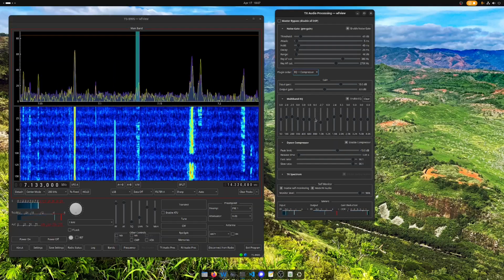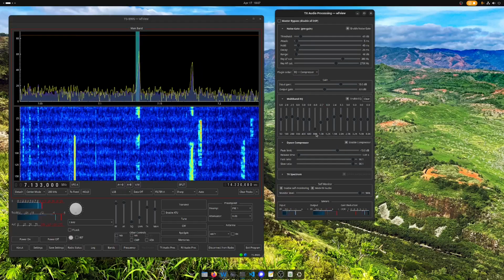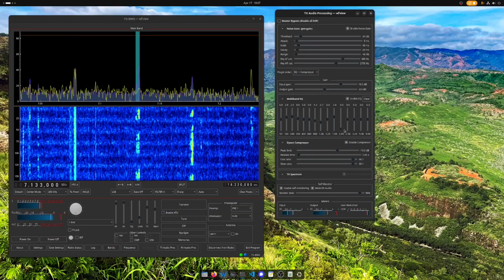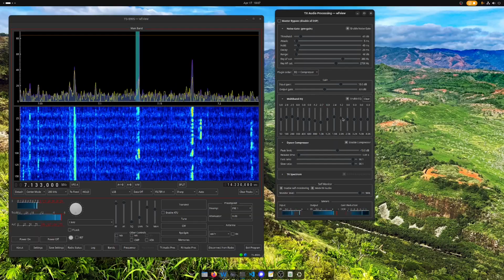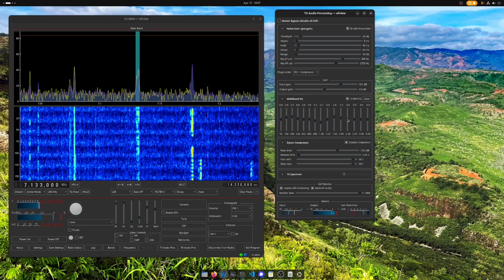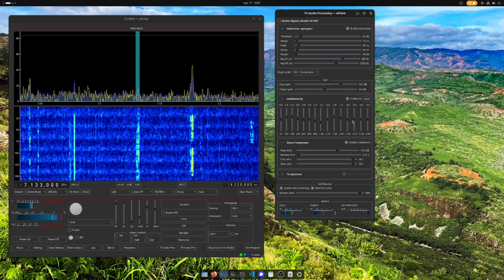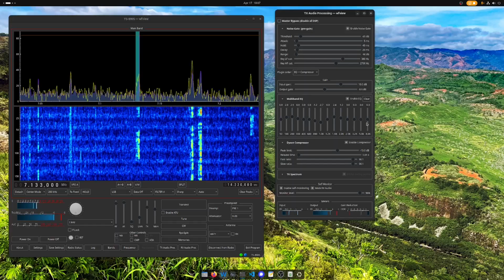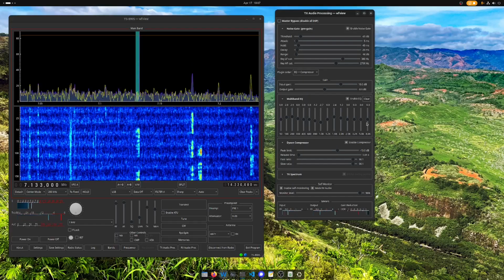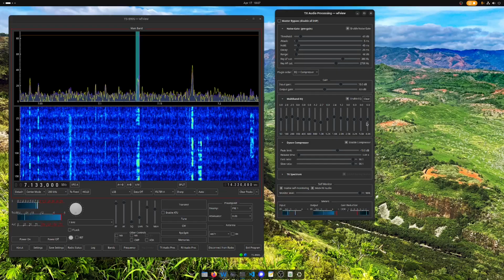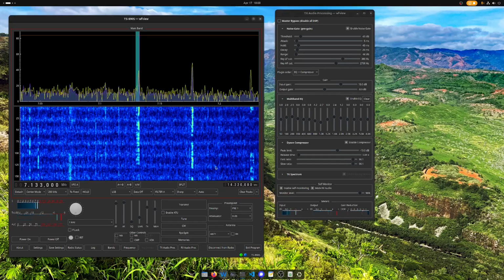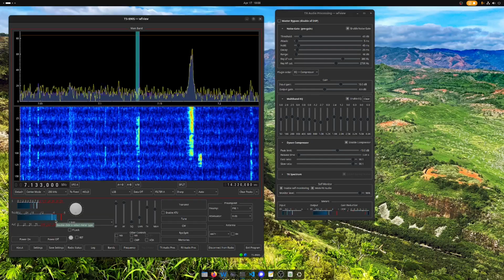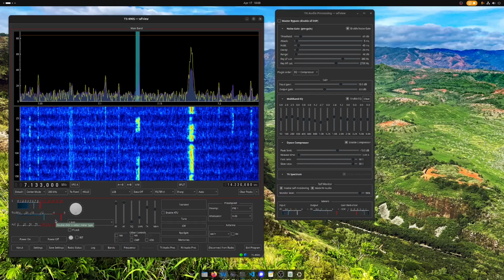So that's how you set up the EQ. You're going to want to listen to each slider, so maybe turn each one up a little bit, turn it down, get an idea of how it sounds. Test, test, 1, 2. And also remember that most radios have a pass band that's going to cut off somewhere around these two sliders here, 2.5, 3K. So don't even bother going higher, even though the audio transport system does send a radio bandwidth that is wider. You're not going to transmit that audio, so that's okay. Now, in terms of setting your levels, once you see that your level is hitting almost full peak, you want to do a transmission on a dummy load and check out the ALC action of the radio.